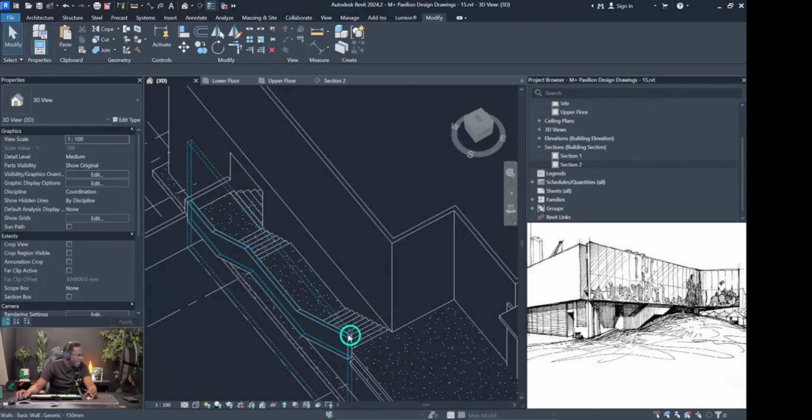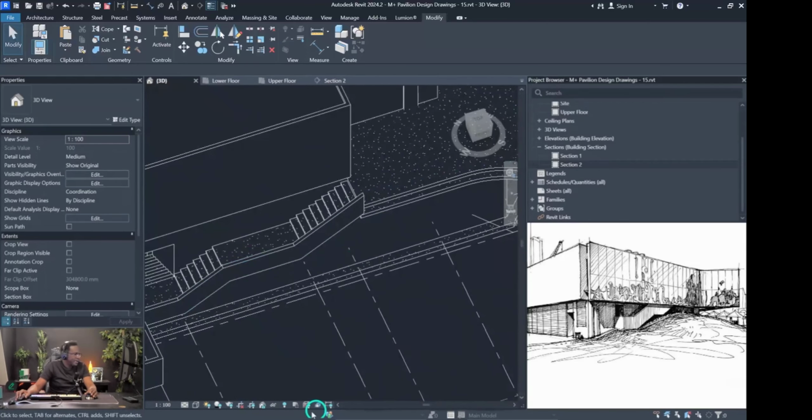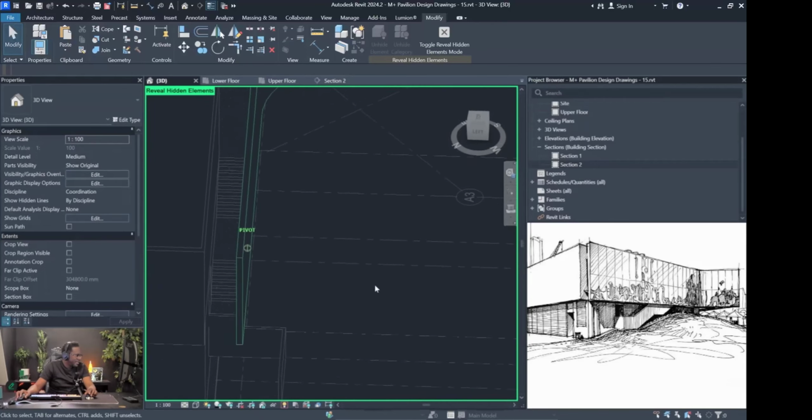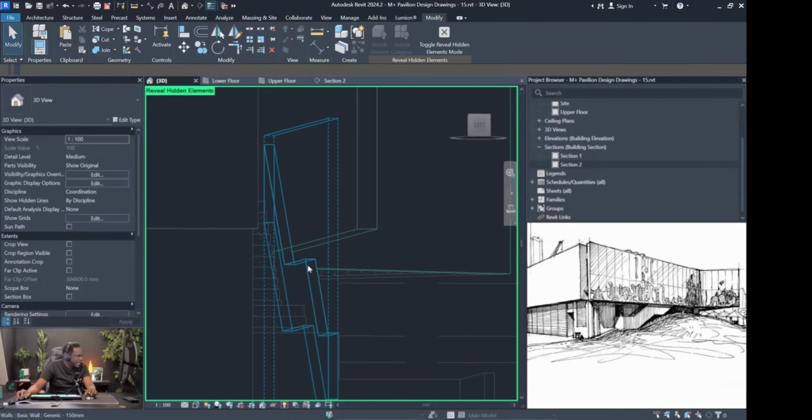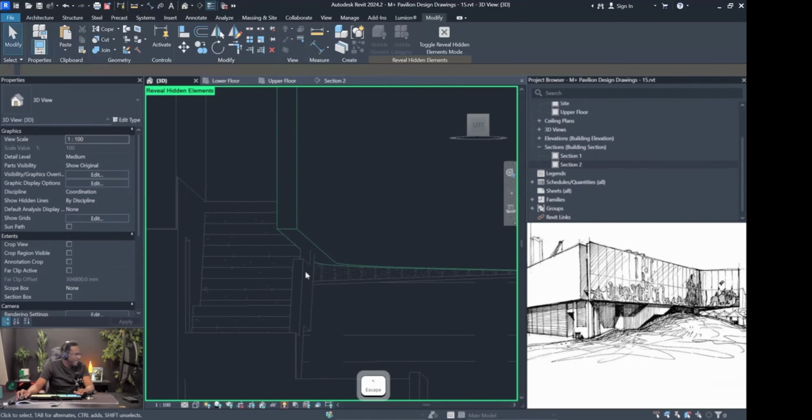The other thing is, I think this should be on the inside of the wall. So let's look at that wall that we hid earlier. That's this green wall here. Right now this is intersecting in the wall there. So I believe that this should actually be on this side here, like that. Hence our stairs needs to actually be shorter. So let's go back to our plan view and tweak our stairs a little bit. We're going to carry these in.